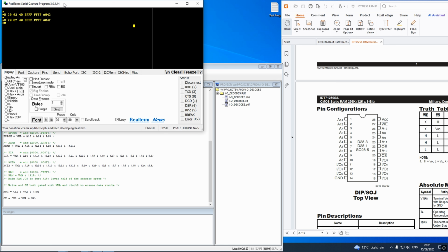M for memory, and an address, say A012, and it displays the contents of that memory. And you just press enter and it will step through each memory address in turn, displaying the content. And it wouldn't do any of this reliably before. It was only kind of taking the command and displaying 1 or 2 characters and giving up.